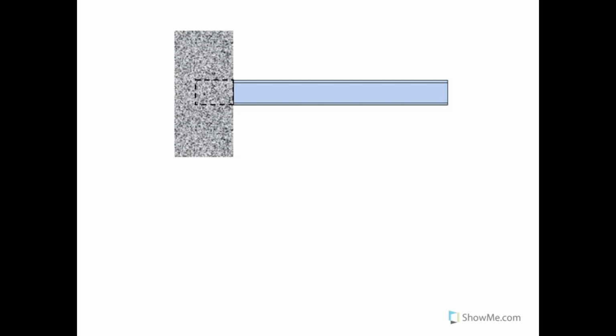So firstly, what is a cantilever? Well, a cantilever is a beam that is fixed at one end, both positionally and rotationally, and it's unsupported at the other end. So what makes this different, for example, to a simply supported beam? Well, let's demonstrate that by drawing the deflected shape under vertical loading. So if you imagine your support there, and we will draw a deflected beam as best I can.